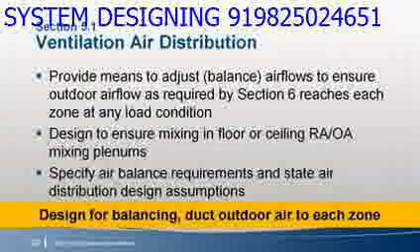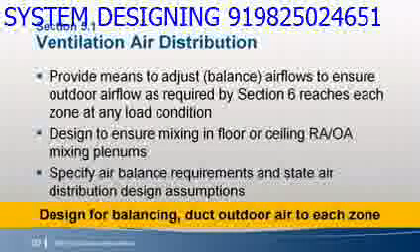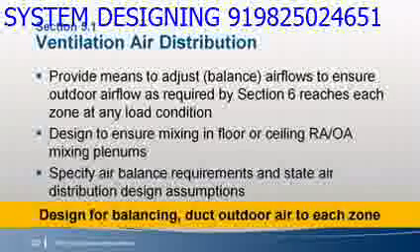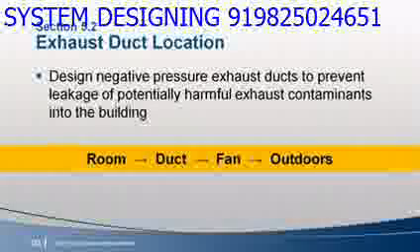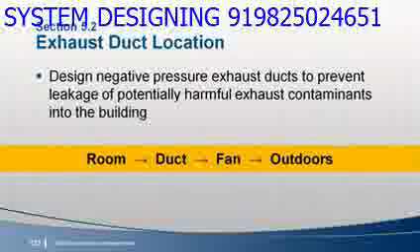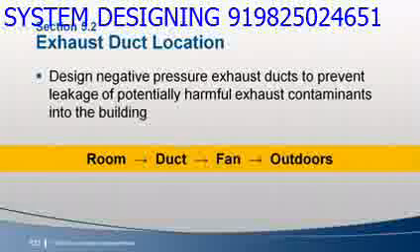Remember that balancing is important, and it's usually best to duct outdoor air directly to each zone in a 100% outdoor air system.